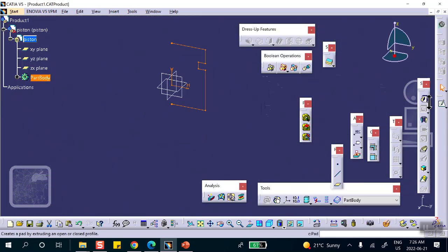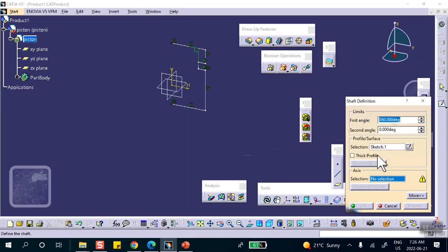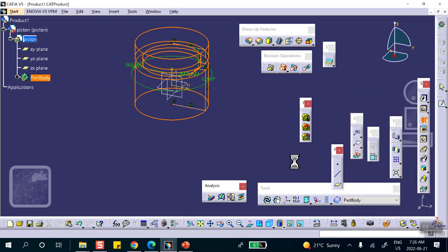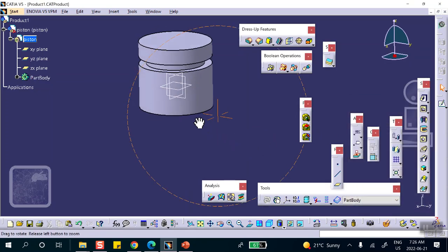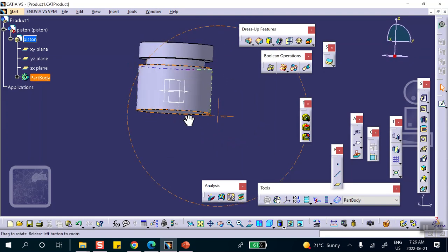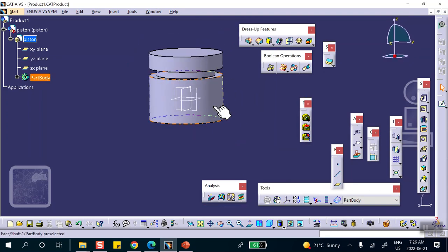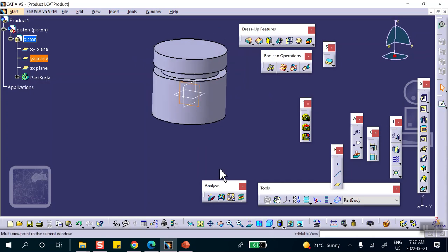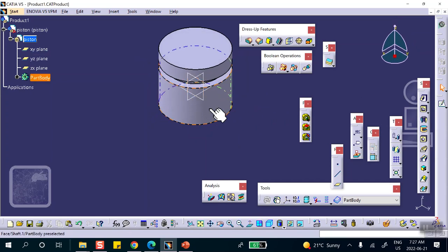The same place that you have a toolbar, that you have a pad, you have the shaft here. It says what is the axis? Axis is Z. Put the cursor there, right click Z axis, 360 degrees. Okay, very good. Except that my piston, I want it to be first of all hollow, and there's going to be some planes here. So let's do the cutouts first. So on that page, let me see, where is the isometric view? There. Okay, so let's make the cutouts there.